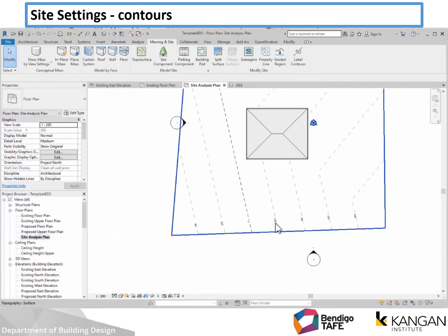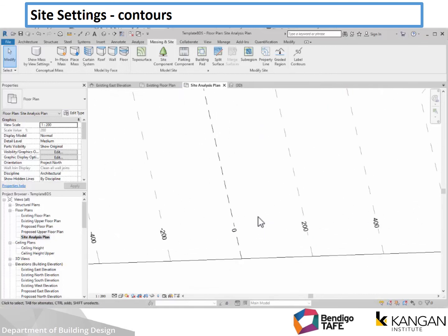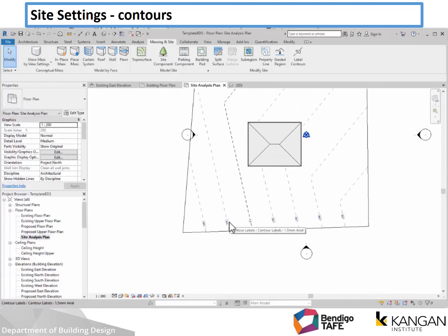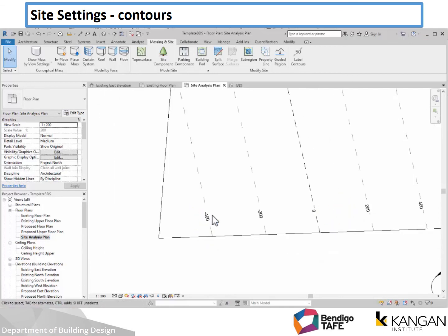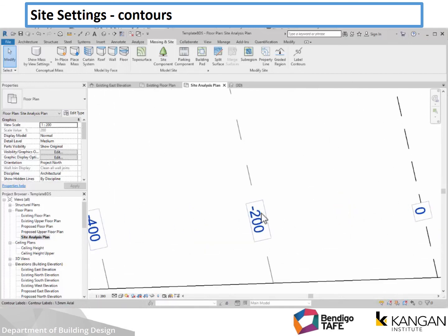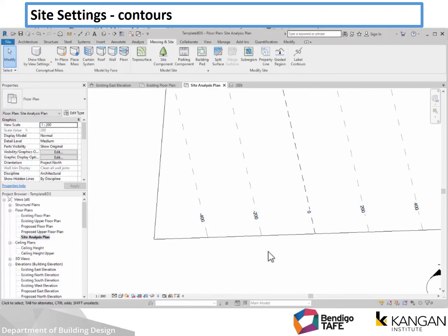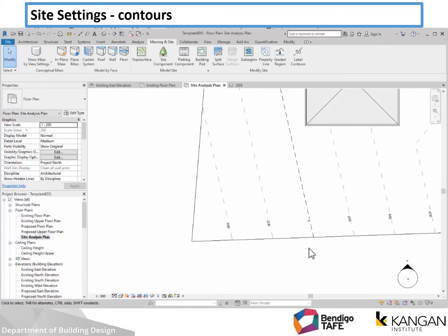Generally, once we set up our building and start working, we'll work the building up around the 100, 200 meter mark so that we don't end up with minus signs. Not preferable, good to test in our template, but minus signs tend to get lost in drawings. We try to avoid using a minus where we can.